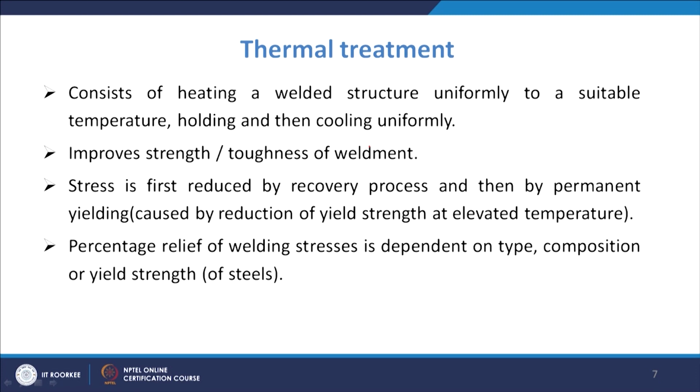It involves heating a welded structure uniformly to a suitable temperature, then holding there, and then cooling uniformly. That results in the relieving of the residual stresses, and that will improve the strength and the toughness of the weldment.